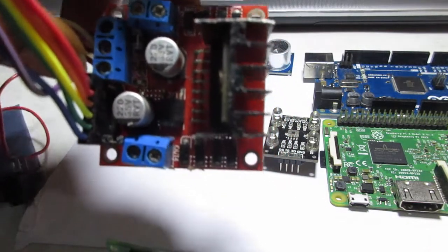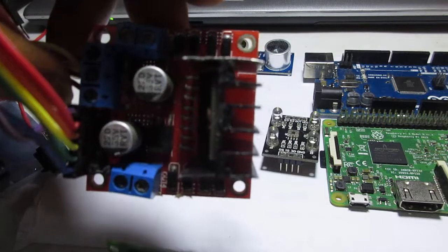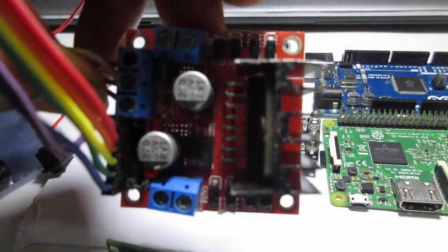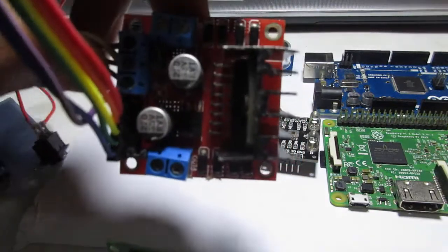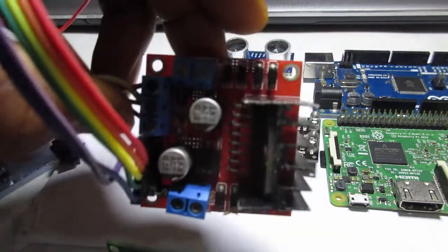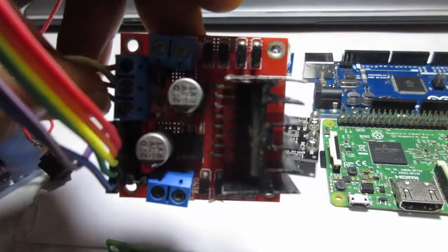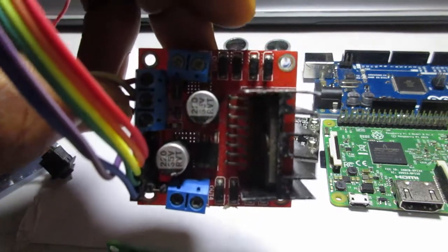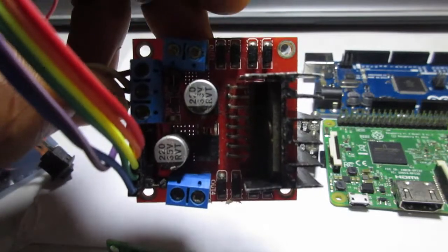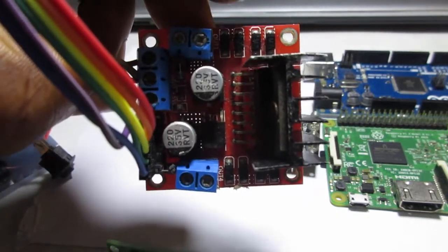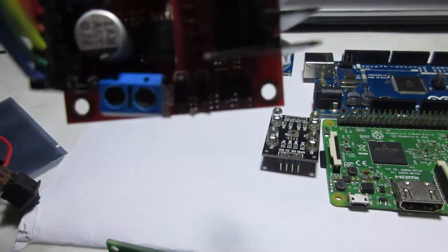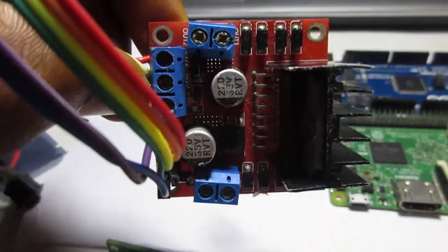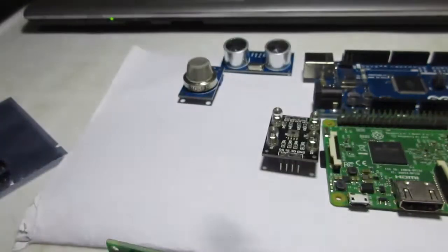You need to power them with an external device that can send a particular current and voltage, maybe to your actuator, your DC motor, or your stepper motor. All those motors can't be powered with your Arduino, because Arduino has limited current it sends to such powerful devices. So you need more powerful devices like this H bridge to power your two motors. You can see we have out 1, then we have out 2. So you use this kind of module to power your motor.